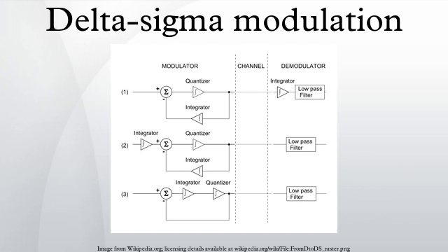Hence it is convenient and fair to represent the input voltage as constant over a few impulses. Consider first the waveforms on the left. 1 is the input, and for this short interval is constant at 0.2 of V. The stream of delta impulses is shown at 2 and the difference between 1 and 2 is shown at 3. This difference is integrated to produce the waveform 4.